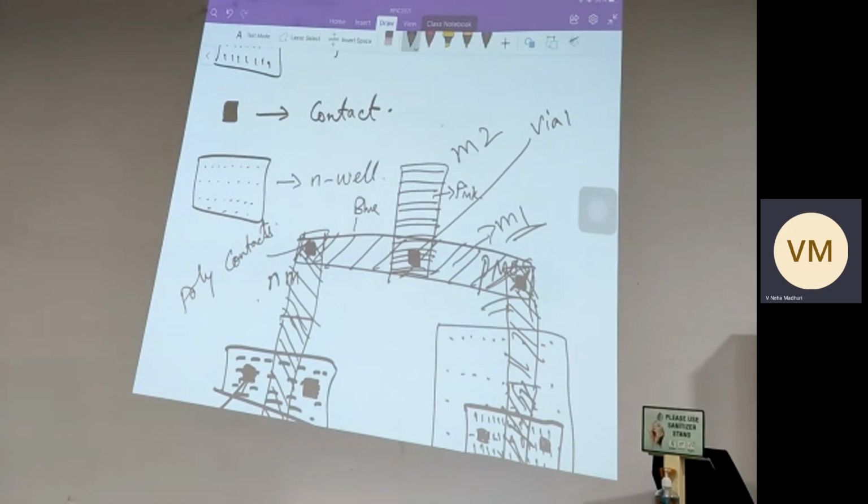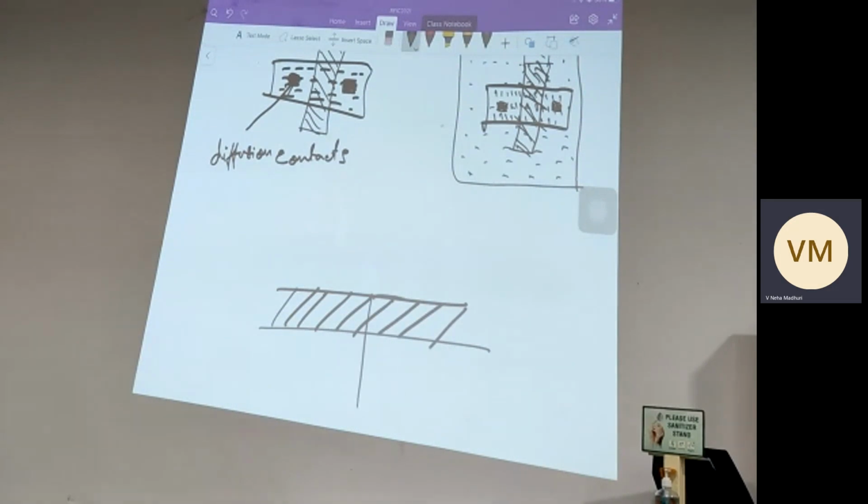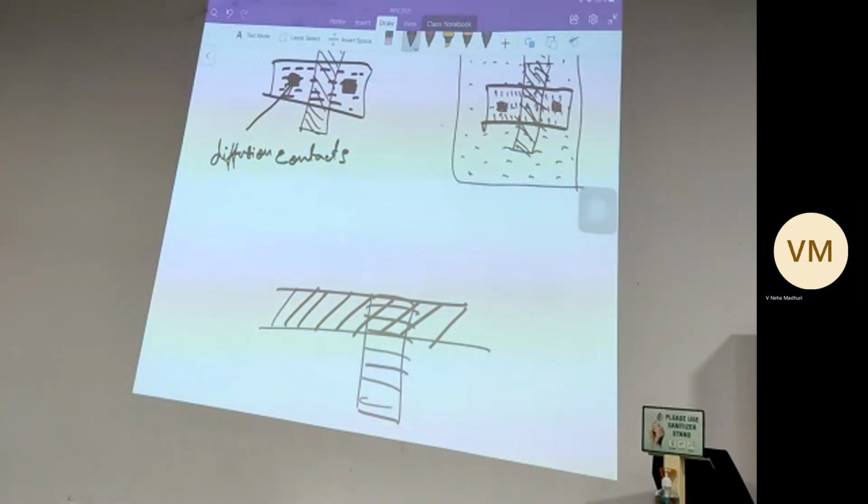We have one. That's it. So now you can say that for this M1 and M2 we have via1. Now I will have another circuit on the same floor, which has M1, and I am connecting this. So this will also be via1 only, because this is telling the fabricator that these holes are made to connect between the same two layers. Okay, clear?